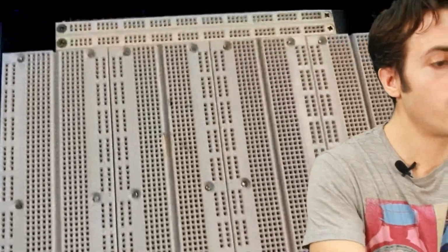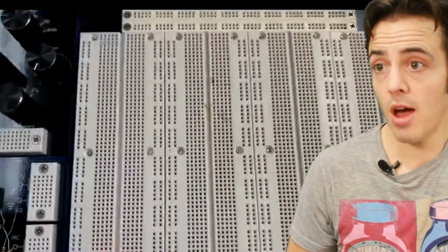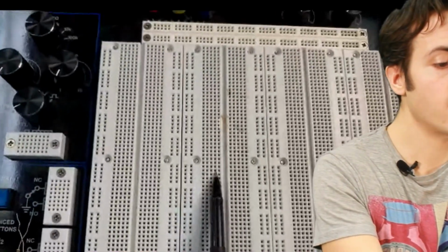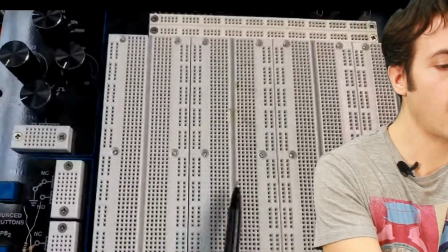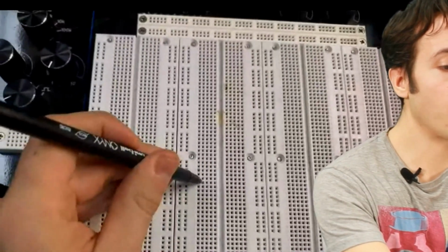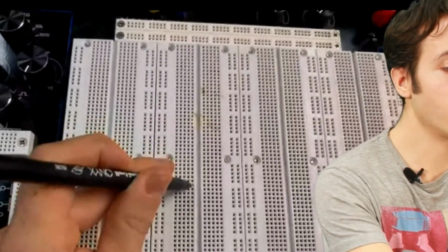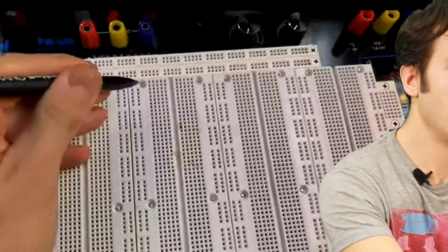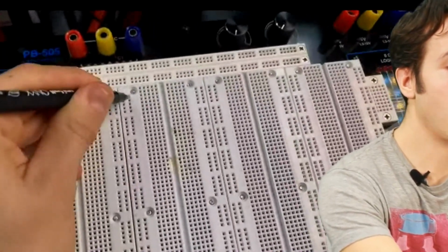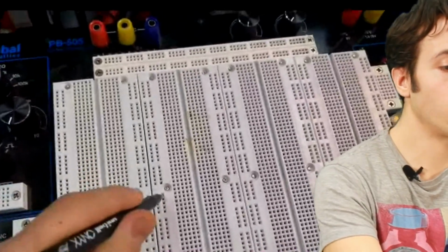What the breadboard is primarily, it's a board on which we can make circuits. Each of these 5 horizontal sets are connected. So if I plug in here, it is at the same potential as this one here. When we go vertically, these are not connected. In these vertical rows that have 2 pairs, they are not connected horizontally, but they are connected vertically all the way down to here, where there's a disconnect, and then all of these are connected.